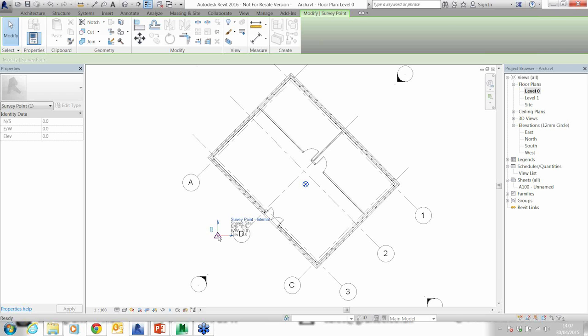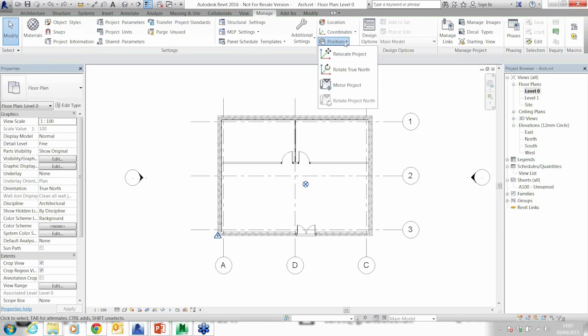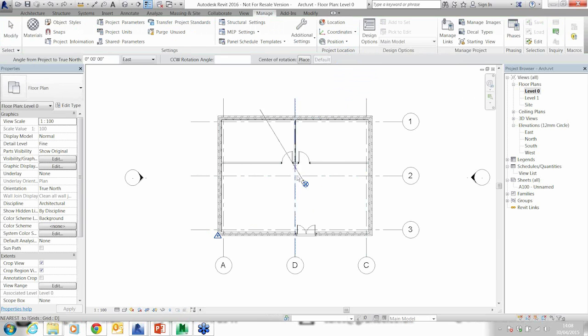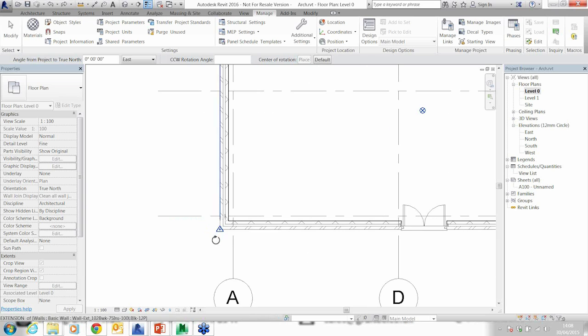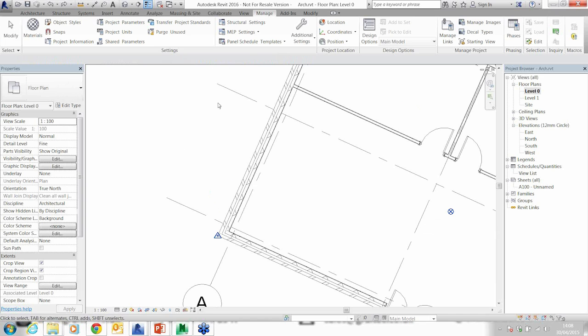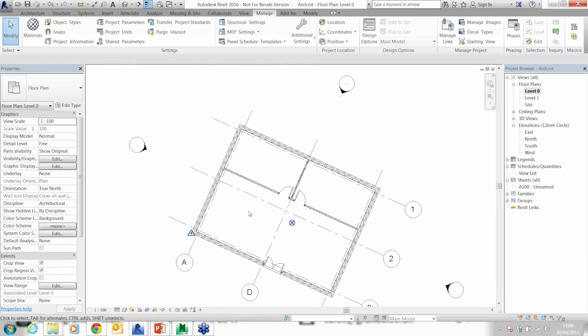I specified that point. Because that is the point I specified, that really should be the point at which I rotate my building round. So just a bit of advice, when you are going to rotate true north, make sure that you place the rotation marker where it is, and point it in the direction of north. If you actually know the rotational angle, then we can set that up as a counterclockwise rotation, or I can simply specify my rotation to true north.